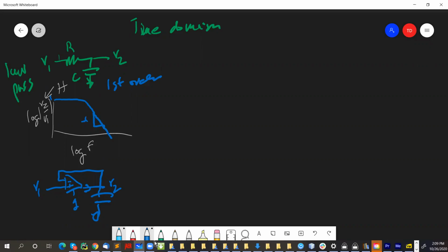Of course, it doesn't consume current at its input like a resistor. That makes it good, actually, in some ways, because it doesn't load down the input with some conductance. You're just driving a gate. But in terms of the circuit property, as long as the signals are small enough that you're in the linear range of this transconductance amplifier, you remember it has this transfer function that looks like this. This is delta V and this is I out. As long as you're in this linear range in the middle, it kind of acts like a resistor. And so that's the CMOS equivalent of this RC low pass filter. Is that clear?